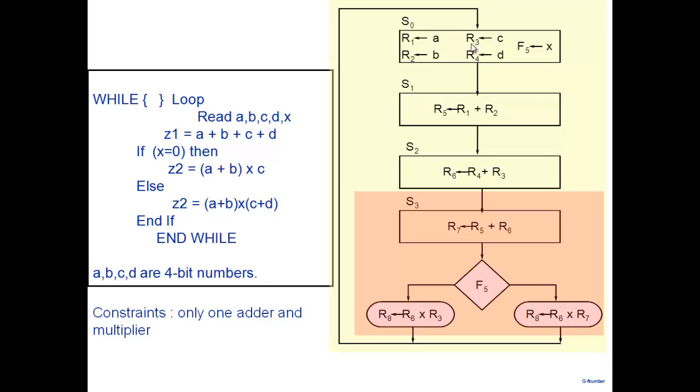So this is a more general picture, where we don't have simply unconditional execution of elementary register transfer operations, but you have conditional ones. So with that, it becomes more general. Now with this more general state picture, any complex computation, for example, let's say a multiplication algorithm by shift and add, the usual way that you do multiplication.